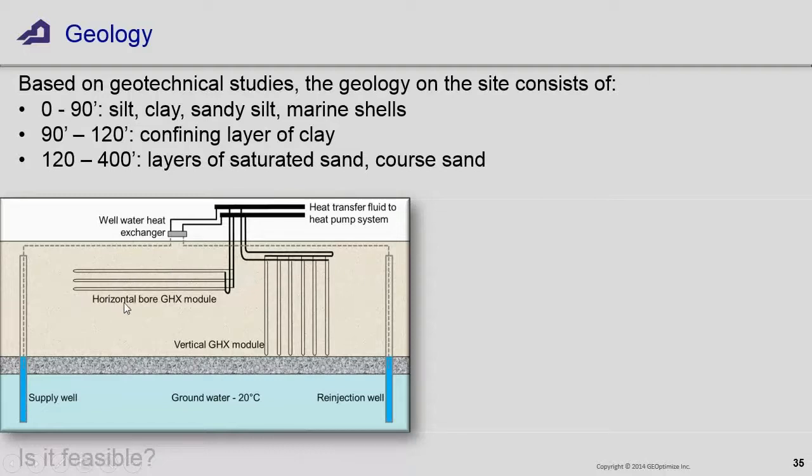So in other words, you can allow the temperature in the ground loop to creep up during the day because it's not large enough to meet the full loads, but it can handle it for 6 or 8 hours, and then you've got 12 or 16 or 18 hours at night to cool it off again for the next day. That kind of thing can work.